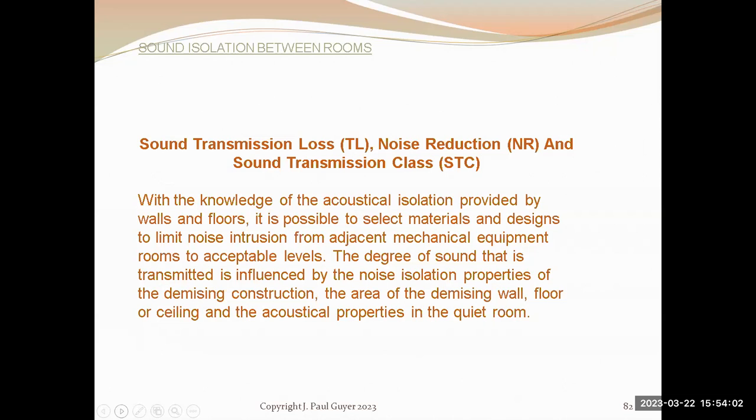And that's where the fiberglass bats come into play, because then the air molecules with a higher level of acoustic energy impinge on these very light fiberglass fibers. The fibers bend and absorb energy, and so you get some sound reduction as a result of having these fiberglass bats in the airspace.